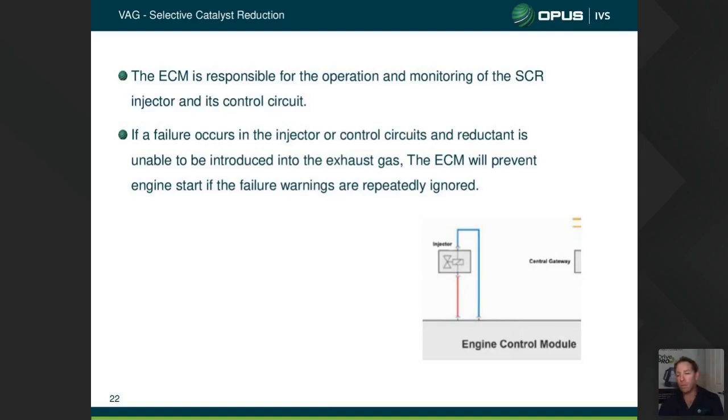If a problem happens with this injector, and it's got to be electrical in nature so that it can be monitored, so open circuit, corrosion, failure of the solenoid, the ECM will warn the driver until it goes, you know what, I've had enough. We're going to shut this down.